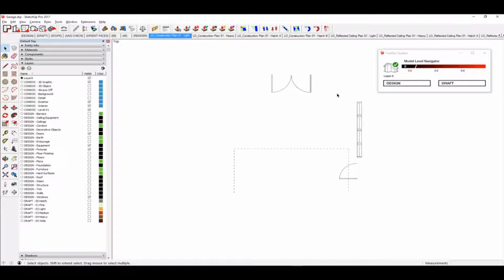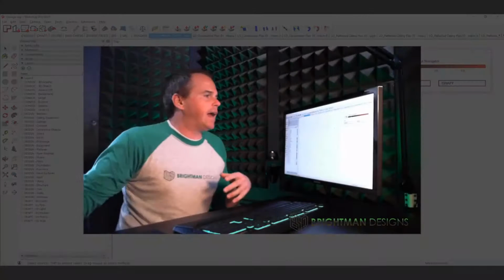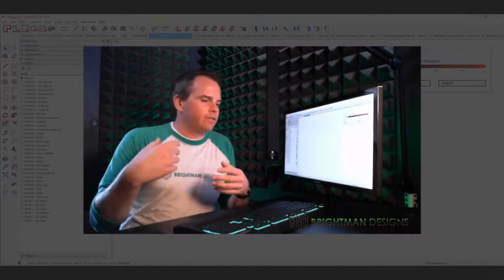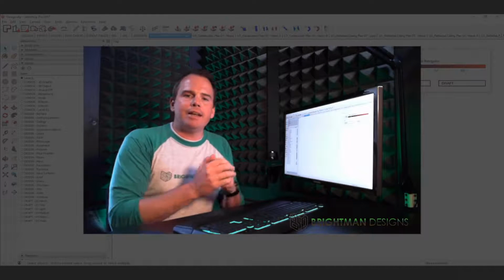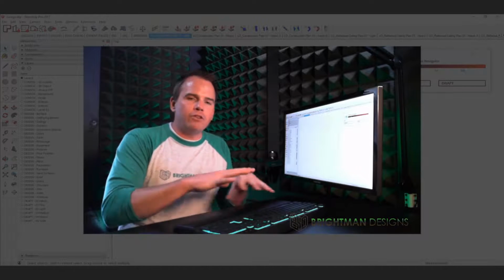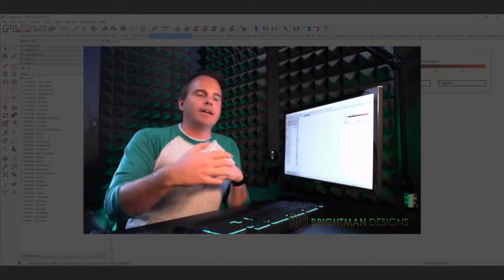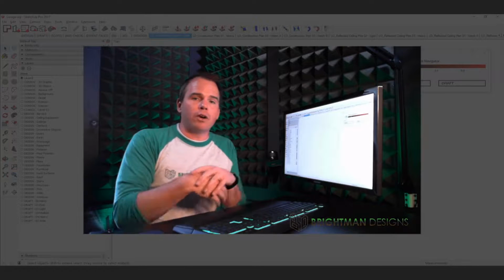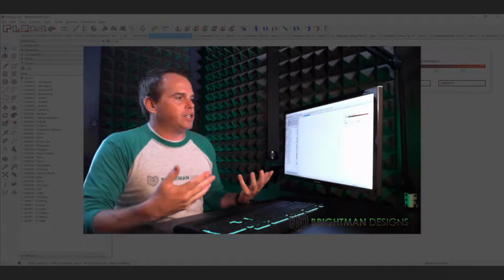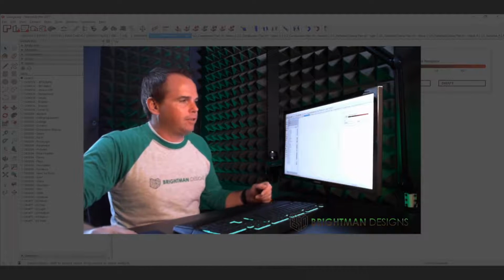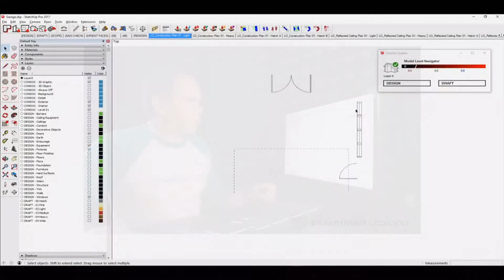my construction plan 01 light, you know, ConDoc automated this process. It laid out all these scenes, flipped a bunch of layers on and off, applied styles, dropped section planes. It automated a ton of work. That is the point of ConDoc, to jumpstart you, to get you to a point where then you can make the drawing you really need. So in this case, maybe I want to see some indication that there's a piece of a structural piece there.